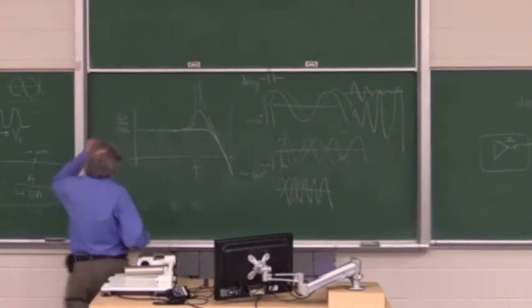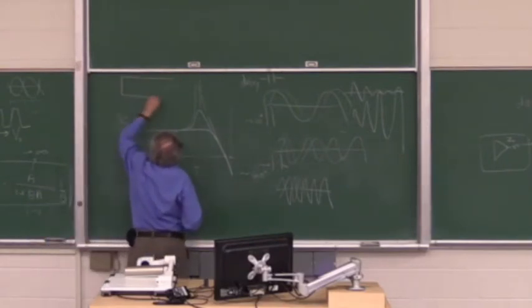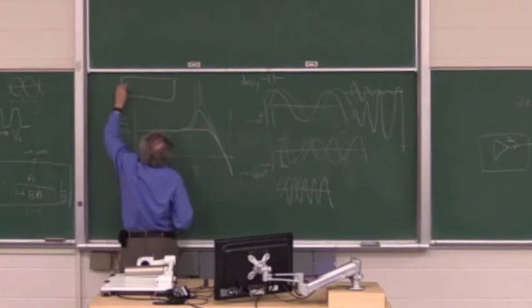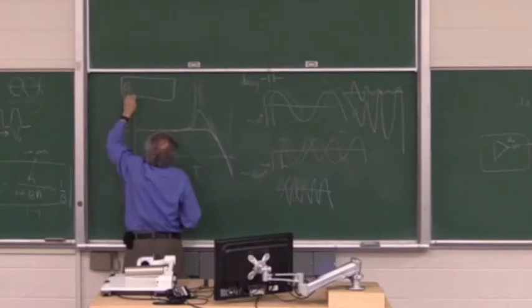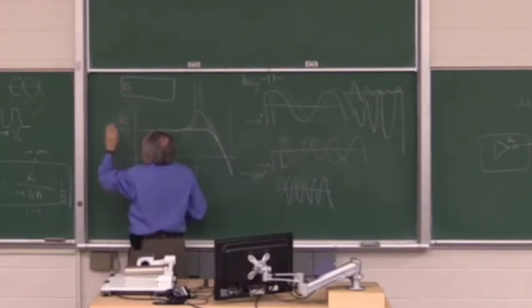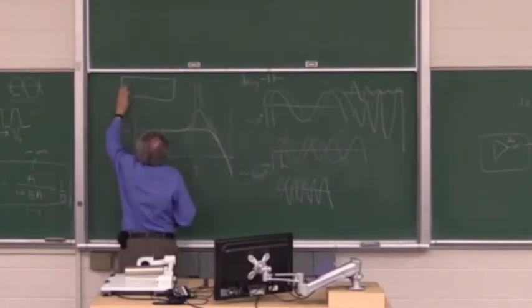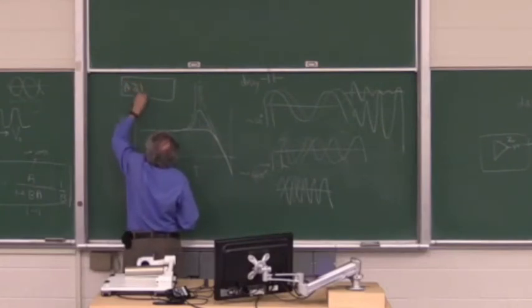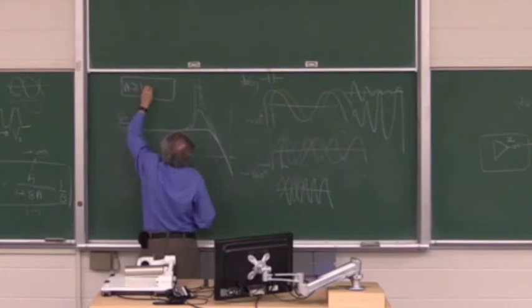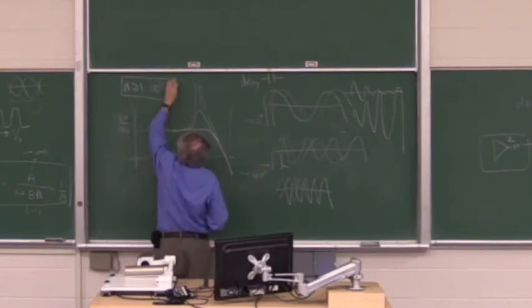So if the gain, G, or the system gain, okay, in this case I called it A, so maybe we stick with A. If A is greater or equal to 1 and there is a 180-degree shift, this is the threshold of oscillation.